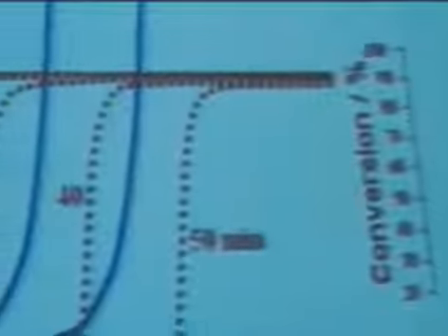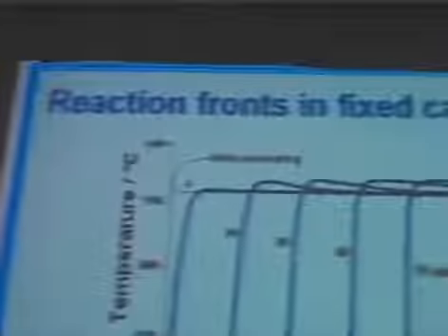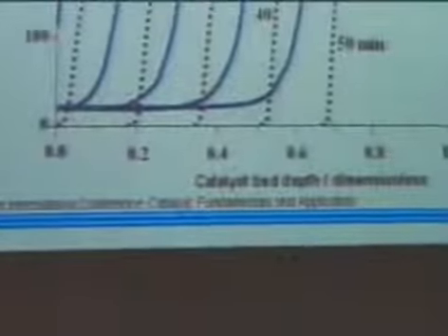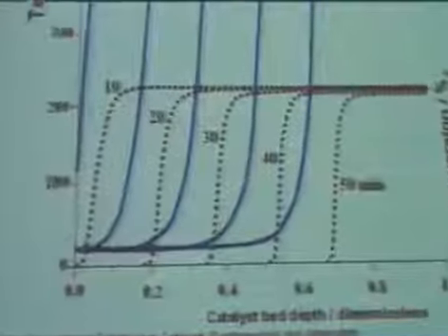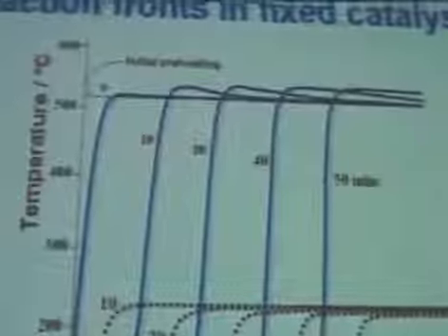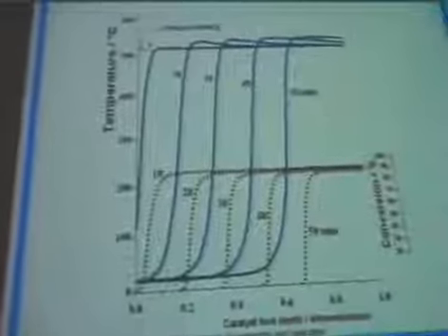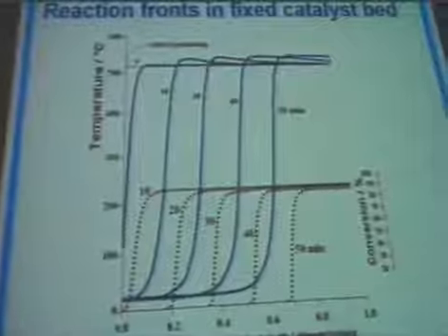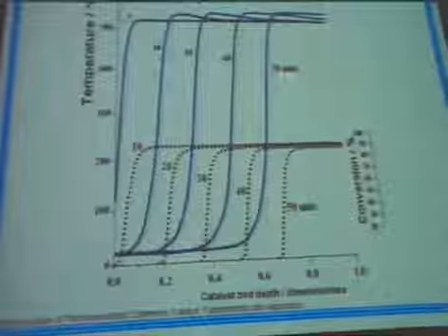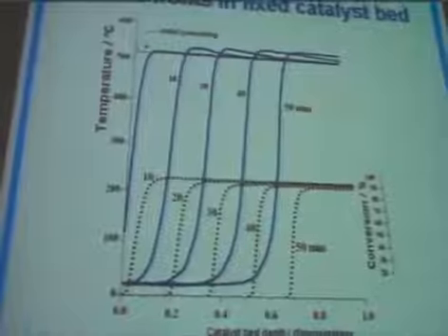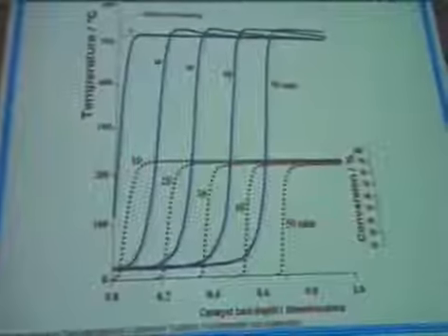Another method to realize unsteady state processes is to have the process in creeping heat waves inside the packed bed of the catalyst. Suppose that we preheated the packed bed of the catalyst to the level where the reaction will take place. Let's give cold gases to the inlet of the reactor. Then after a very short time, you will see the formation of a creeping heat wave along the packed bed of the catalyst. It's a good idea to realize this phenomenon, that at cold inlet temperature you can see high temperature inside the packed bed of the catalyst.